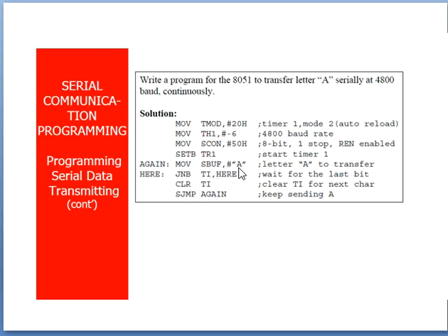So here I am speaking of the bits of the character. Each letter has a certain ASCII value, and that ASCII value has a bit pattern. Like if I have the value 50H, it has the pattern 0101 followed by all zeros. So this is an 8-bit pattern. These 8 bits have to be loaded into the SBUF register. Once all the bits are loaded, TI goes high, indicating that all the bits of this character are loaded and we can proceed with the next thing. So this is how this program is going to execute.